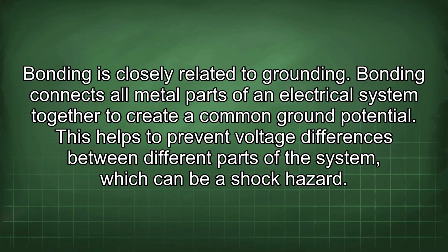Bonding is closely related to grounding. Bonding connects all metal parts of an electrical system together to create a common ground potential. This helps to prevent voltage differences between different parts of the system, which can be a shock hazard.